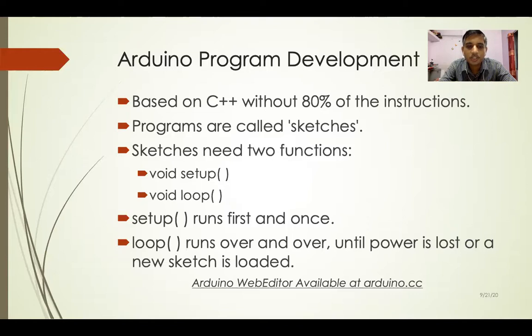The loop function is nothing but a while(1) loop, just like the one we write in embedded programming. The loop function will be called an infinite number of times. Whatever you write inside the loop function will execute continuously again and again. There is no need to put a while(1) inside the loop, because the loop will be called infinitely by the main function.